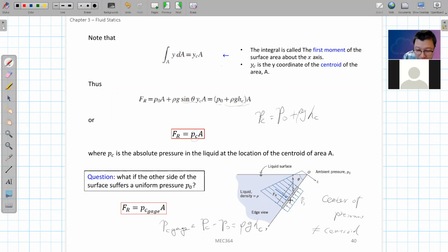So we need to find, if we reduce all this parallel pressure force to a single resultant pressure force F_R, how we can find the point of application for this force. Would the center of pressure equal the centroid if there was an even distribution of forces? Yeah, if the pressure force is evenly distributed, it will be equal. But it's not. You see that this is right.